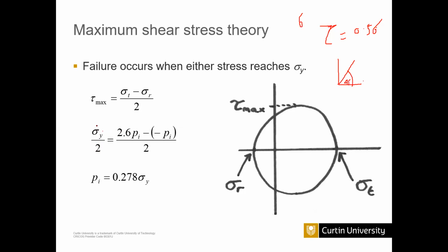So this is the maximum shear, yield strength divided by 2, and we already know the stresses at that point. It is like a sigma 1, this is like a sigma 2, it is minus p. Just substitute that one. Then we get the values of pi from this side, and simplify that equation until this point. Then you will get this kind of relationship between the internal pressure and yield strength.